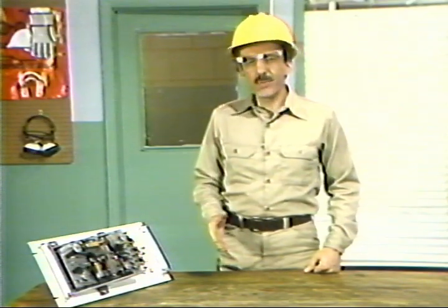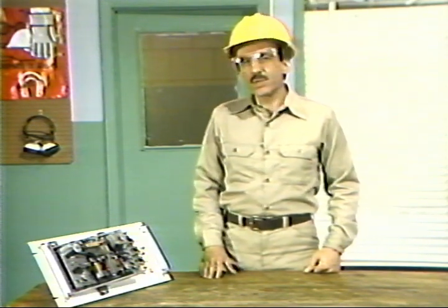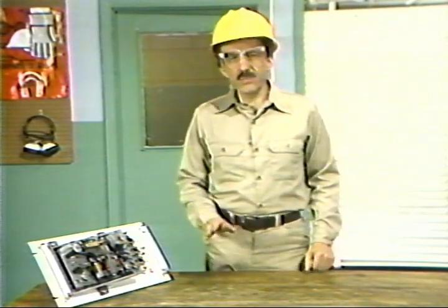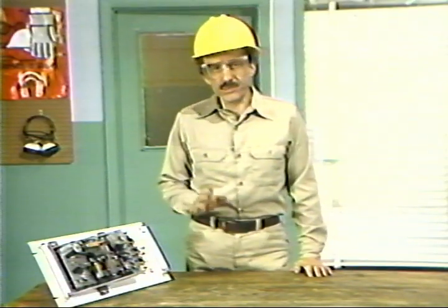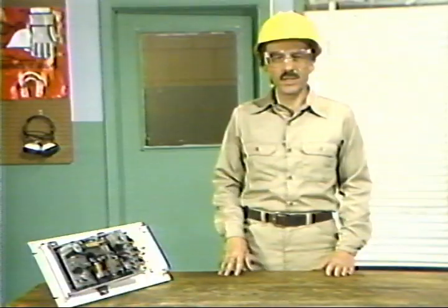Up till now, we've examined pneumatic controllers that provide just one or two control modes. We'll look now at a controller that provides all three modes: proportional, plus reset, plus rate. Now, this type of controller is commonly referred to as a three-mode controller. A three-mode controller incorporates proportional action to match changes in a process variable, reset action to eliminate offset, and rate action to quickly stop deviations in the process variable from set point.